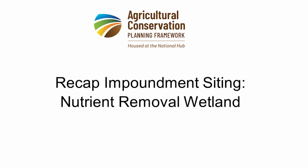To recap, we ran the Nutrient Removal Wetland Tool and discussed how we can use the results to determine the actual structure of our wetlands. In the next video, we will run the next impoundment siting tool, farm ponds.